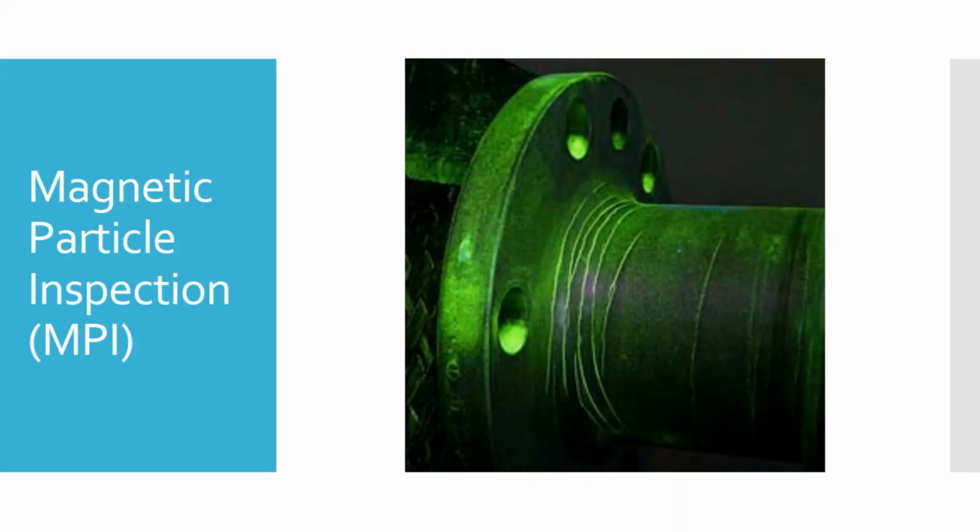What about the fact that the whole surface is glowing? What's causing that? Okay, this is mag particles. So these are actually magnetic particles that are in a liquid. The surface finish is a rough finish, so it's going to trap a certain amount of that stuff. So is that relevant, non-relevant, or false? That's a non-relevant indication. Okay, so in this image, there really aren't any false. You've got non-relevant in terms of the particles collecting in the bolt holes.